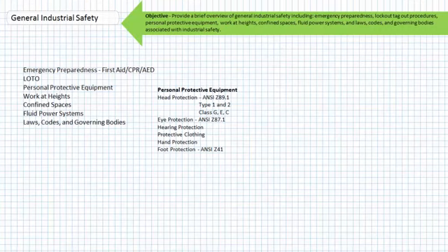The same advice holds true for rubber gloves that are often used as insulators for electrical work. Different gloves have different voltage ratings, and you need to use the glove with the right rating. Rubber gloves are especially fragile, and even a pinhole leak renders the whole glove useless as an insulator. It is for this reason they're supplied with leather overgloves. A quick and easy function test on the inner rubber layer is to see if air trapped in them leaks out. If so, get a new pair, because these won't protect you against electrical hazards.